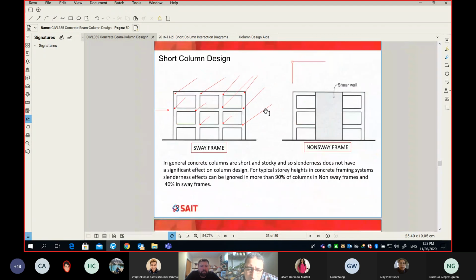At a very high level, without further ado, the difference between the left picture and right picture is the connection. This connection here simply looks like this in our analysis. In our detail, in our construction, it's a hinge. We don't carry load from beam to column. How about the one on the left?